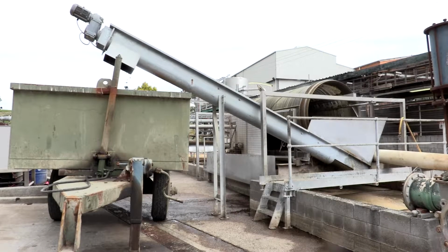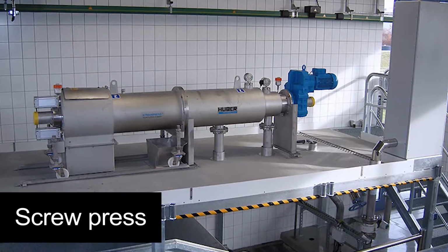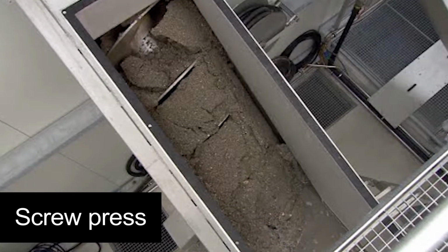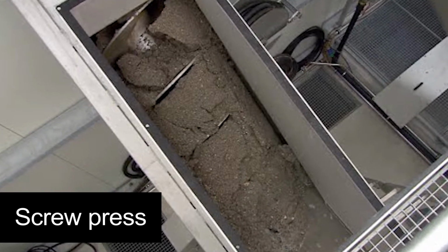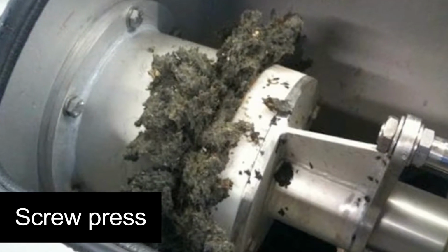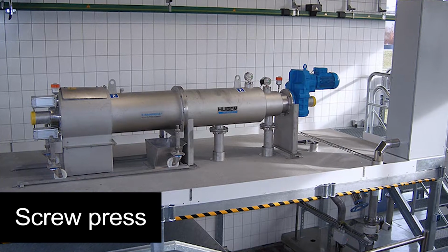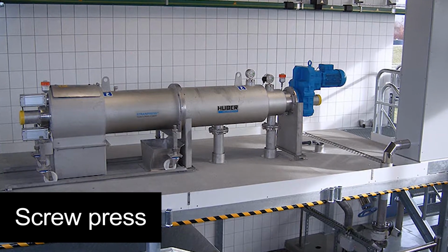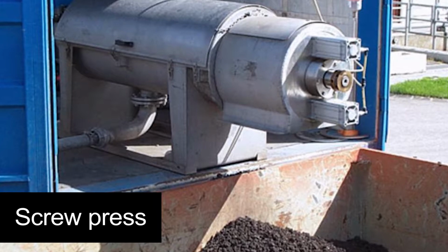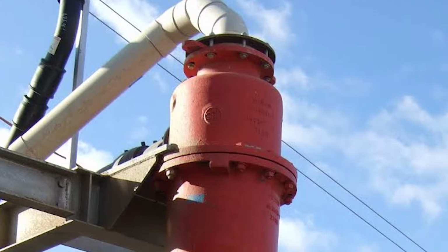Both static and rotary screens can be blinded by fats and are susceptible to overflowing. A screw press is a rotating screw in a barrel. At the inlet end, wastewater passes through a screen for initial dewatering. At the other end, compressed solids form a plug, against which the incoming solids are compressed for even further dewatering. This device is highly effective at dewatering fibrous solids such as manure and paunch. The discharged solids can be quite dry to touch. This generally reduces solid waste disposal costs, particularly those based on weight.